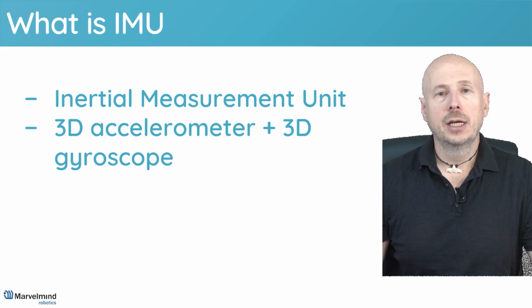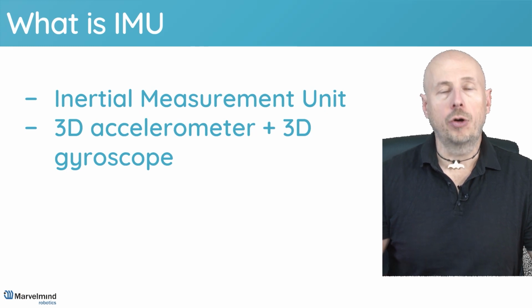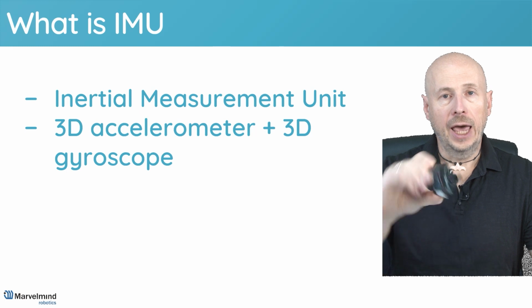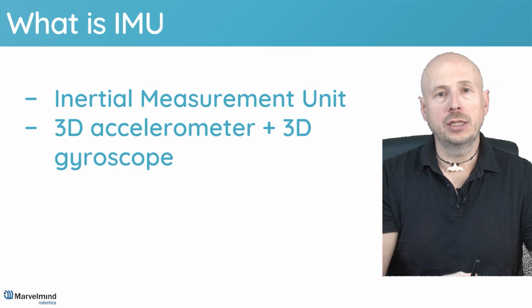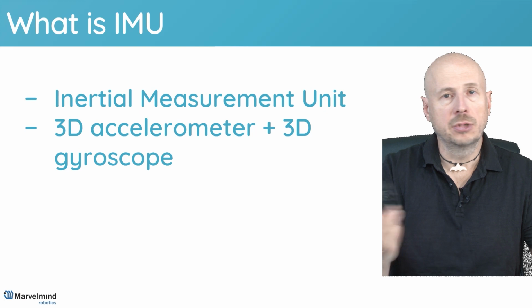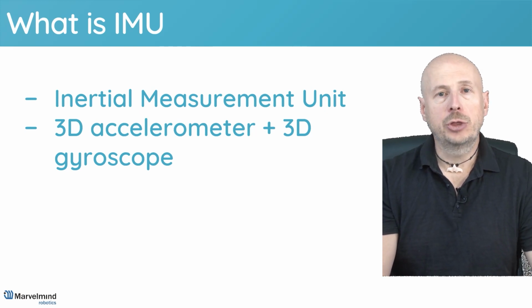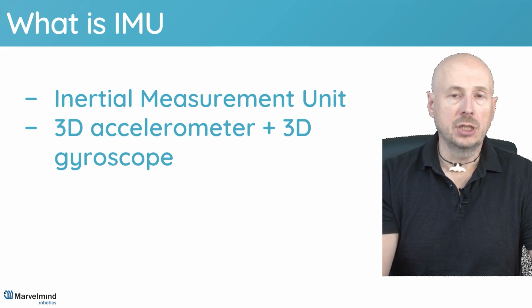Let me highlight that when we talk about IMU and positioning and why it's complex, we mean complex to achieve location. Angle, just raw angle data or measuring acceleration, is nothing, you can get it. It's a very, very basic functionality. But to measure the location using IMU is an extremely complex task. To measure the absolute angle is also a complex task, but significantly less complex.